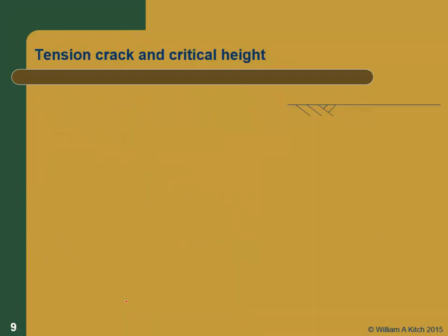All right. So there's a couple important implications of this. One thing that everybody knows is that if we go by someplace that's clay, you go out to the dry lake beds, and you see cracks in the ground. Why do you see cracks in the ground? Because they're cohesive soils, and they stand up with no lateral earth pressure. In fact, you can go some places, and those things are really, really deep. I mean, people could stand in them if they were wide enough. You can certainly take a meter stick and stick it way down those things. So we know this happens, right?